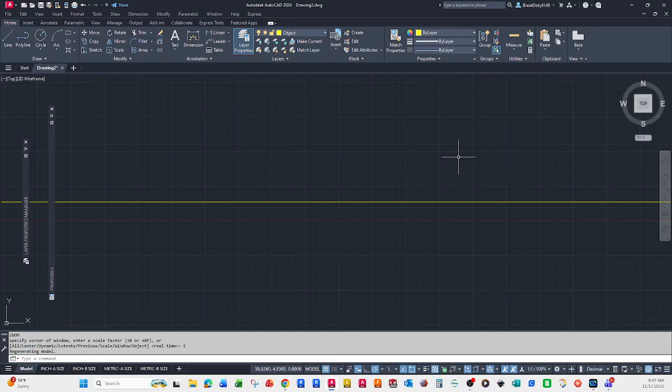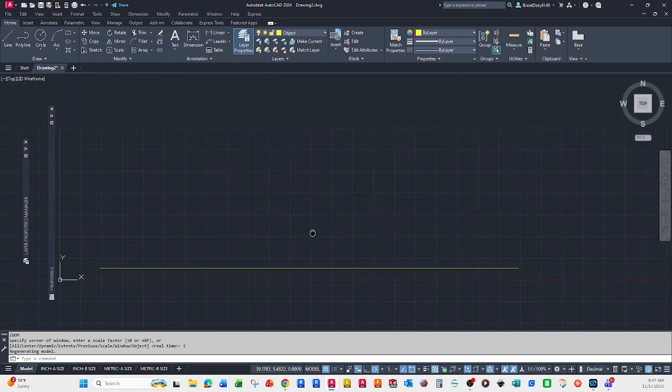So I did zoom extents, and see, I drew it 150 long, right? So, but it'll work. And now I have a little extra room, so if I did need something that big, I'd be in good shape. So anyway, that's limits, and that's basically, you think about your units. Is it metric? Is it inch? How big is it? Is it going to fit inside of a 12 wide by 9 tall square or rectangle? And if it won't, then you need to go into limits.